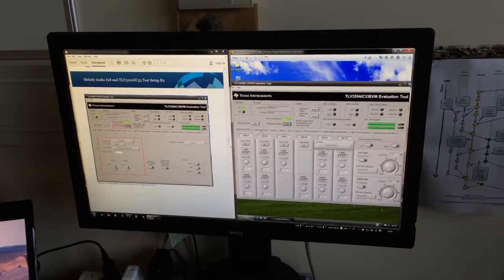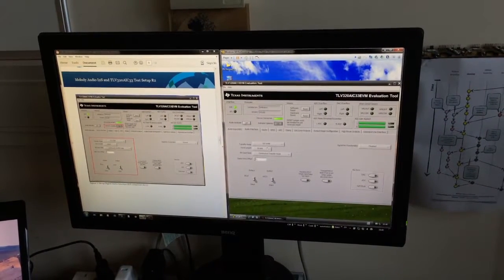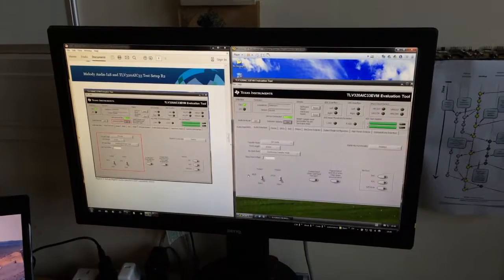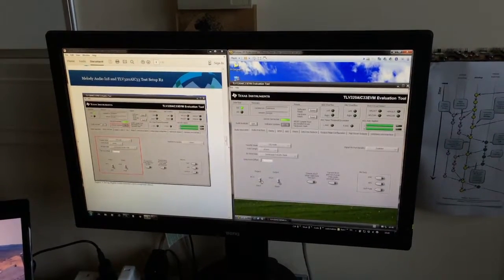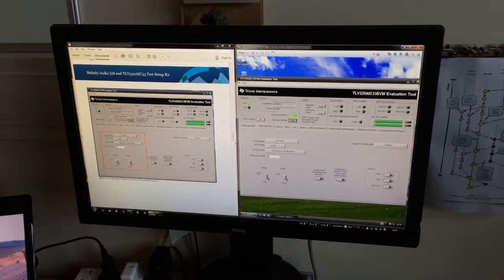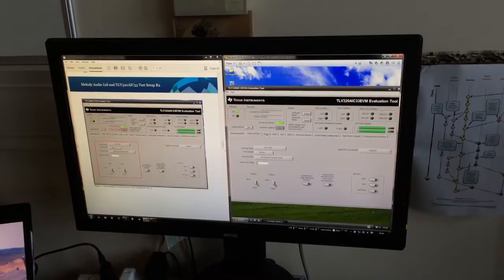I'm now going to configure the audio interface. We are going to use I2S, 16 bits continuous transfer mode, and we have a 1-bit clock delay as per the I2S specification. The bit clock and the word clock are inputs since Melody is master, so we're done with this pane.